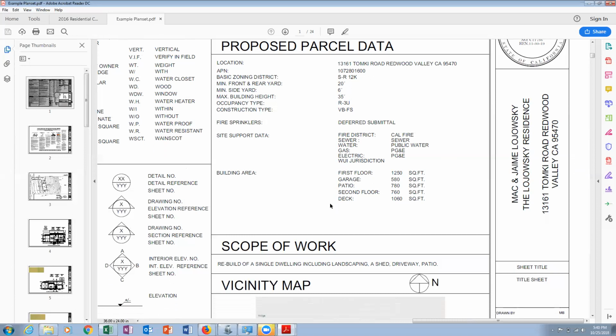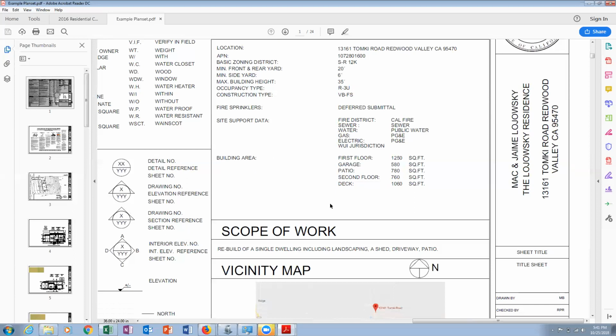Great question. The garage is considered an indirectly conditioned space. So we're going to model the garage, and basically the one wall that connects the house to the garage is going to be modeled as an interior partition wall. So the energy modeling software will understand that that wall is not actually getting the full climate from the outside of it. It's getting like a more controlled climate from the garage. So the modeling software will understand that when we select it as a garage, and it'll perform a little bit better because that's like a buffer zone for the house.